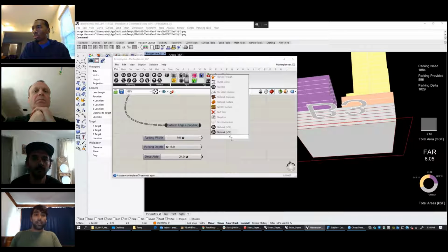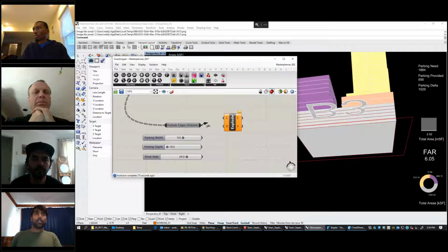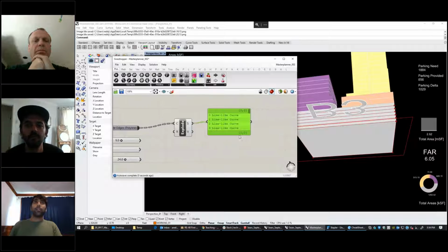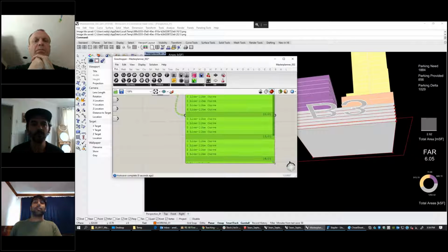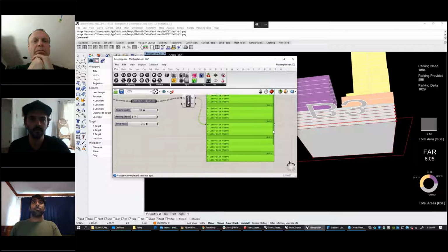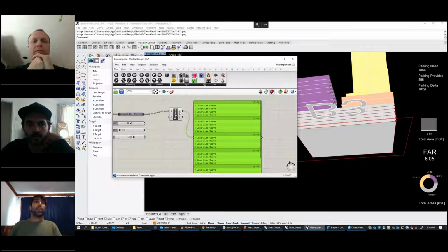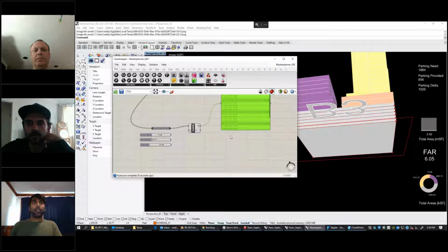So let's say we've got our outside edges, and we want to explode these outside edges. And so now if we use a panel and look at what do we have, 5 branches, because we have 5 levels, or 6 branches, 6 levels with all 4 sides in each branch, right? And we can even simplify that if we just use the simplify command to make it just a 0, 1, 2, 3 for the names of those branches. I just like keeping it kind of organized, because then we can always come back and say, level 1, level 2, level 3.